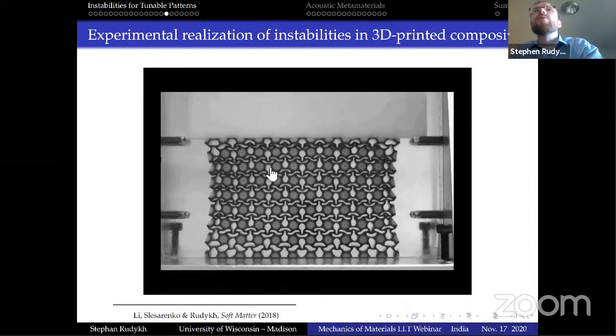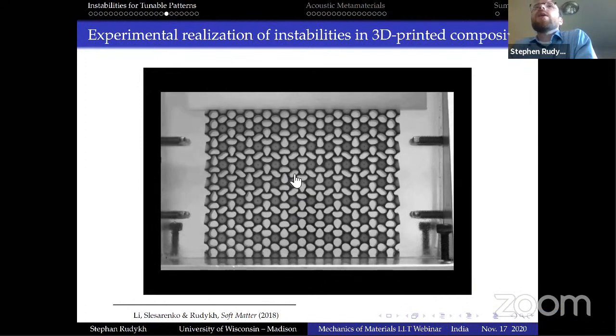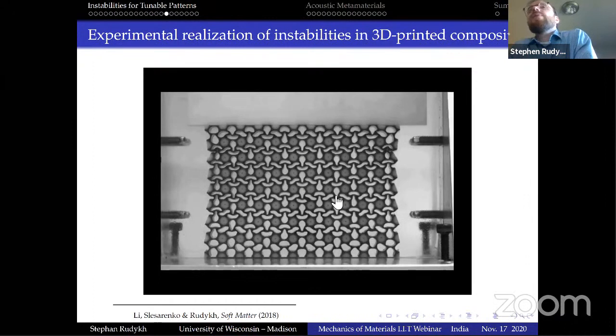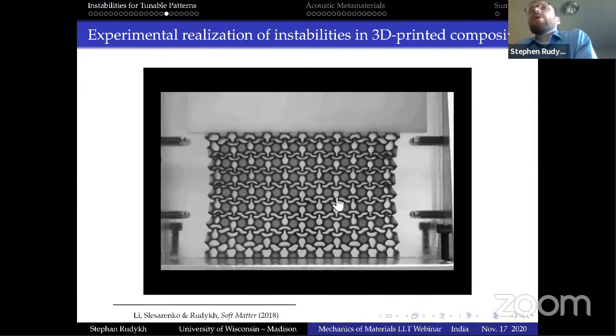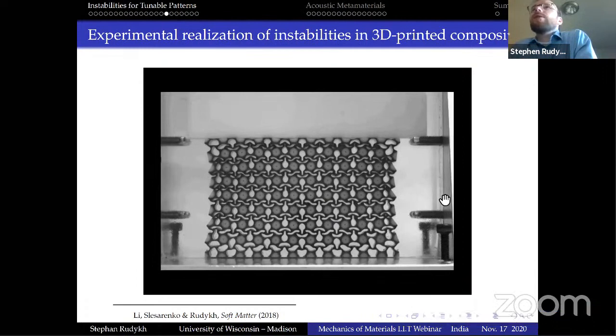So you break that pattern and you force the material to go elsewhere. The one thing that you notice here, again based on the behavior of material with periodic voids, is that when the voids collapse, that also exerts negative Poisson ratio behavior, right? We compress it in this direction, and the material doesn't expand in the other direction. That is the characteristic of that.